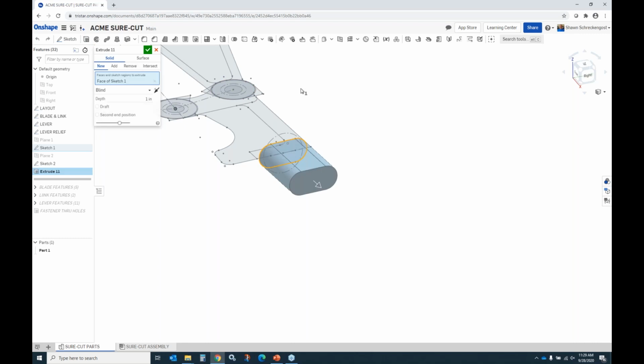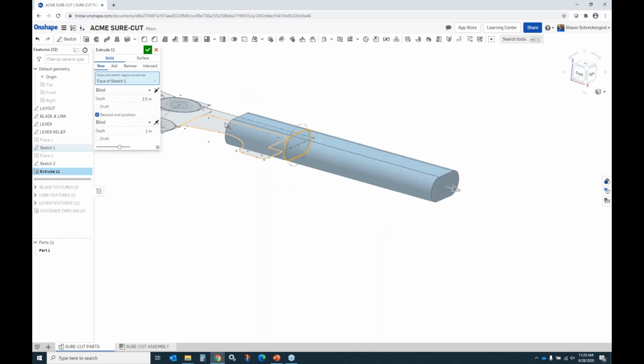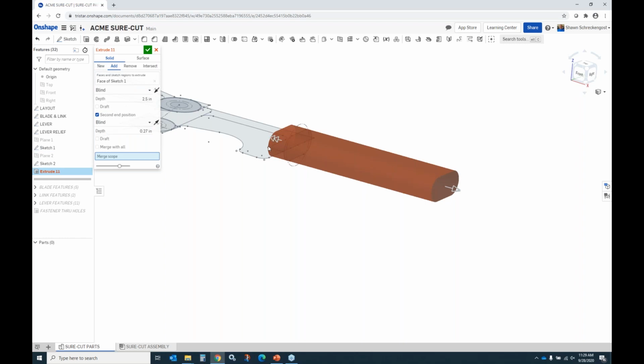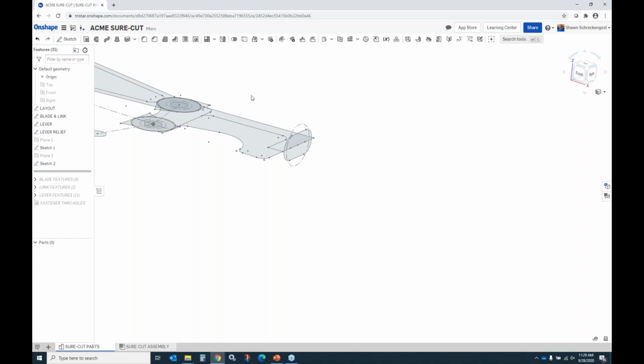So we'll go ahead and hit the extrude here, and I can extrude that to some length, right? Now what I'm going to do is I want to specify that that is 0.25, and I also want to give it a second direction. Okay. Now, by default, this wants to create, in this case, a new part. I'm going to add this to an existing part, and I want to turn on the part that I'm going to add it to, which is going to be, whoops. You might need to roll forward. Yeah, let me roll forward.